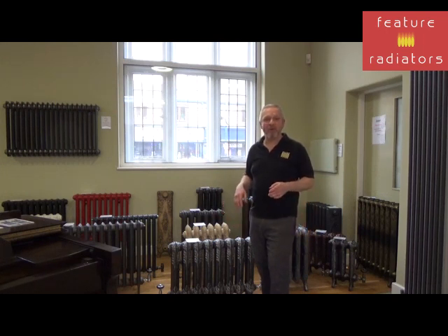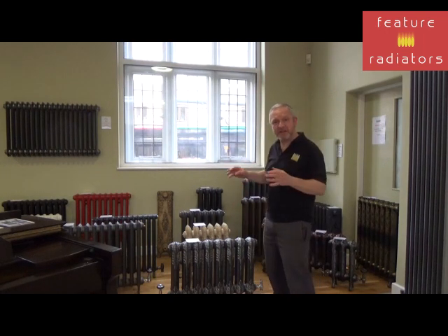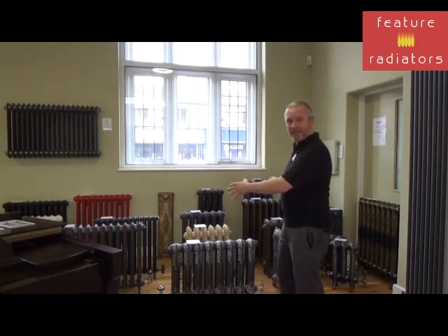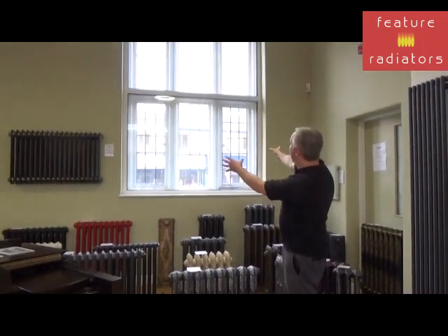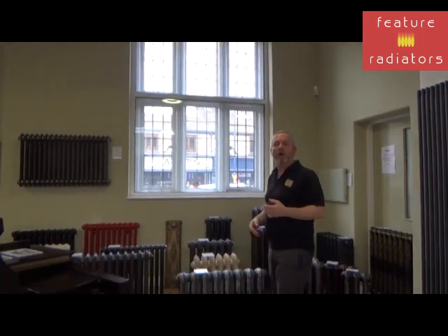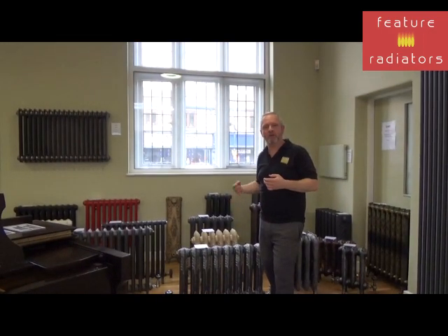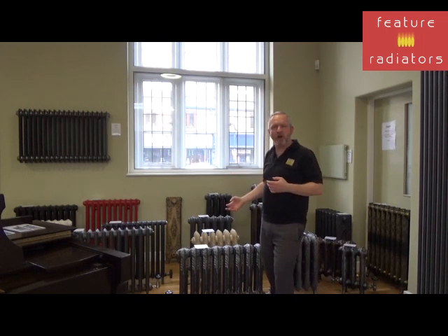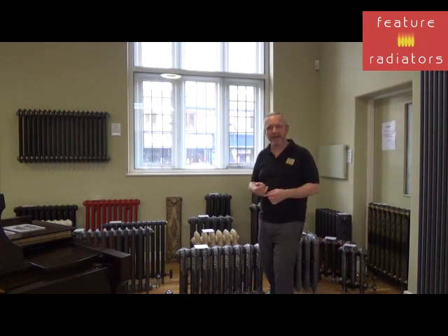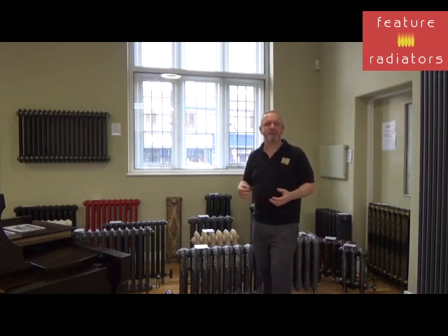And windows are important because if you've got some large expanses of glass, so for example, if you imagine this is our living room, and we've got some nice radiators in the living room, that would be considered a large amount of glass, and it's not like a normal wall in a house, it's quite a cold spot in the room, so you need to factor that in. French doors will make a difference too. So anything like that, I'm normally adding about 10% on top of the calculation, even if it's for double glazing, plus a further 10%.